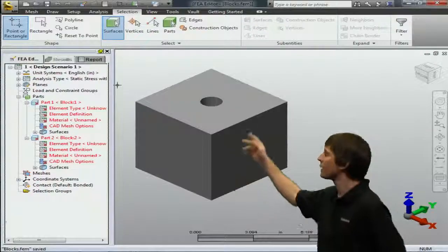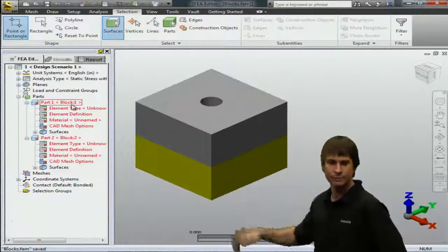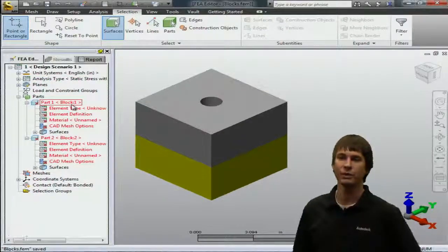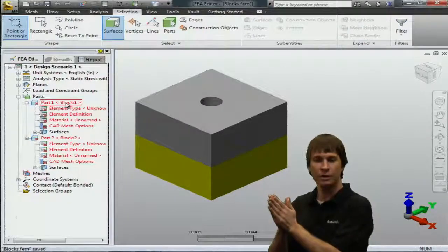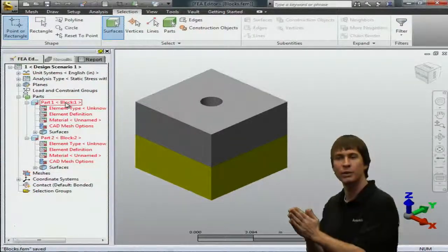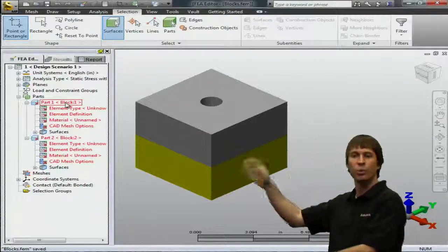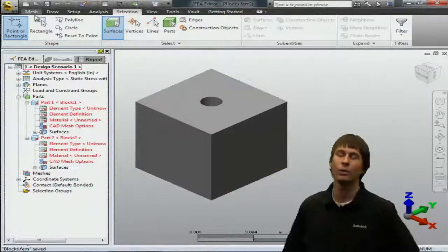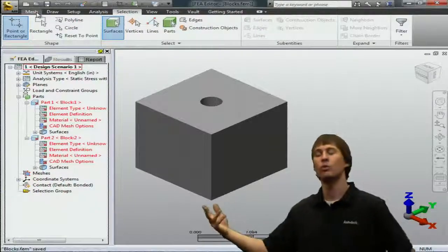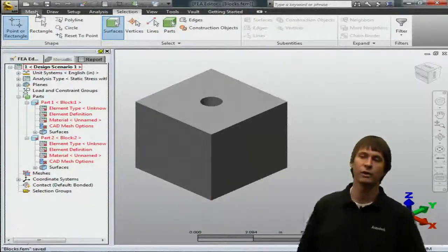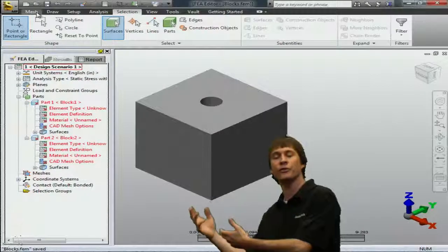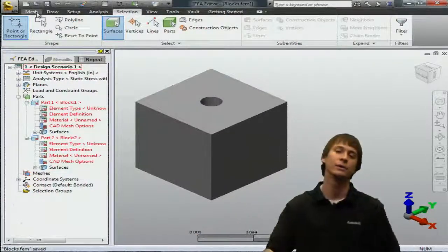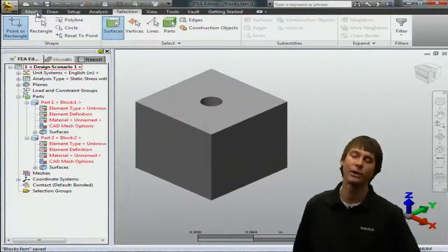So you can see here that we have two solid parts that we're going to be working with. Say these parts aren't bonded together, maybe they have surface contact, but we don't want them to move. Well, we can put a bolt in here to tie them together. Why don't we just do that in CAD? Well, then you bring over a bolt that has a whole bunch of elements, makes your model run a lot slower, and just imagine if the threading was modeled in there. I bet all of you are using that with the threading, right? Well, we don't want to do that.